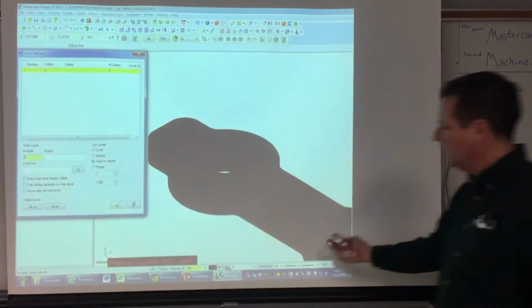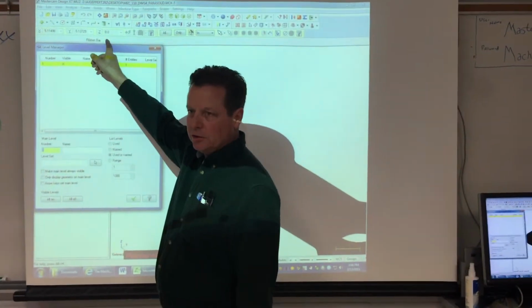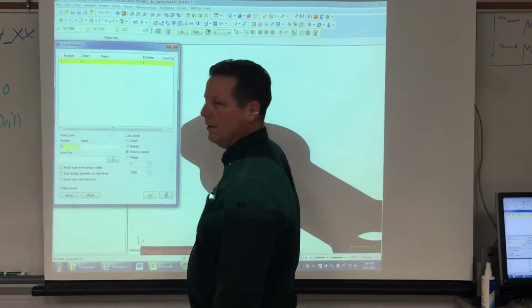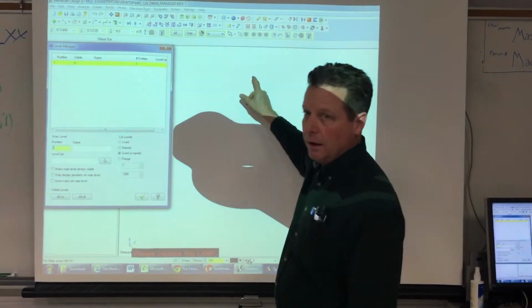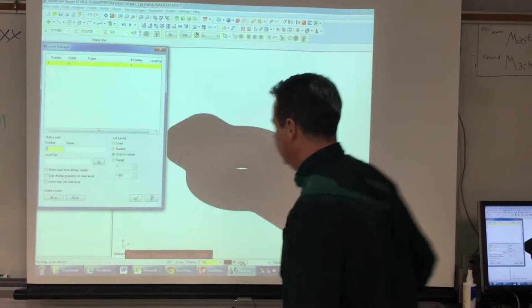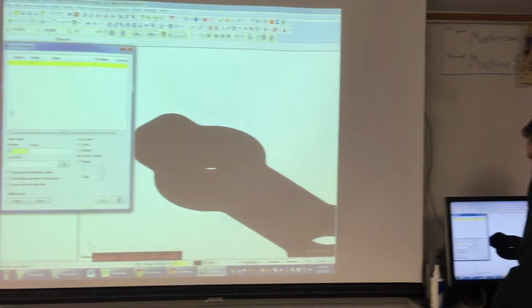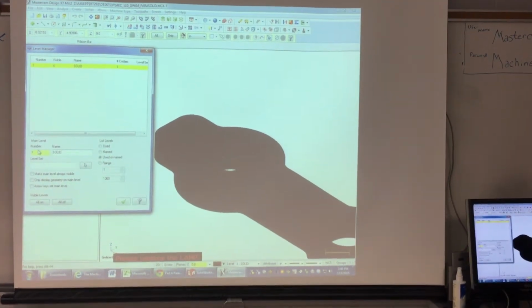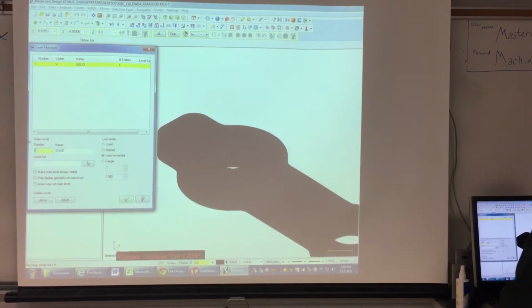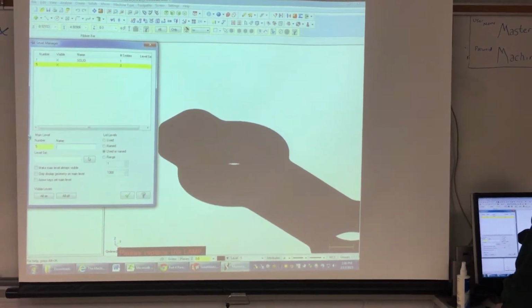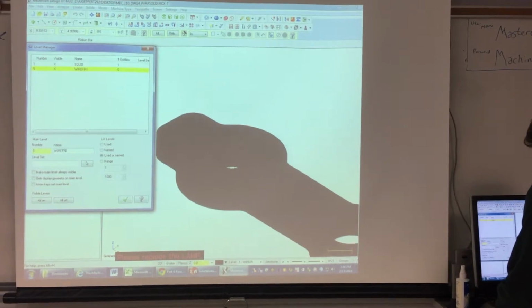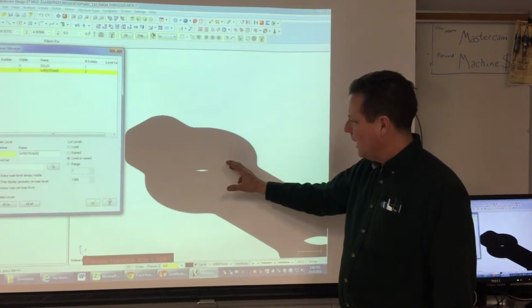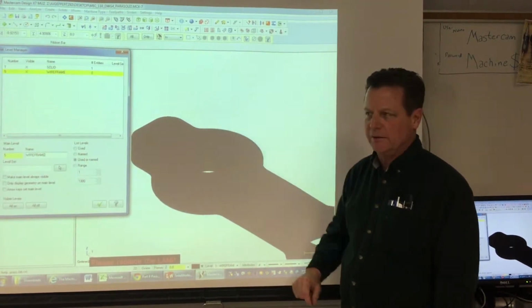What I did next was I opened up the Levels Manager by left-clicking on it. Right now I only have one dumb solid in Mastercam, so I'm going to name level number 1 Solid, S-O-L-I-D. Then I'm going to do a new numbered level 5, I'm going to call wireframe. And I'm going to use Mastercam to grab this model and put a curve on all edges of it.